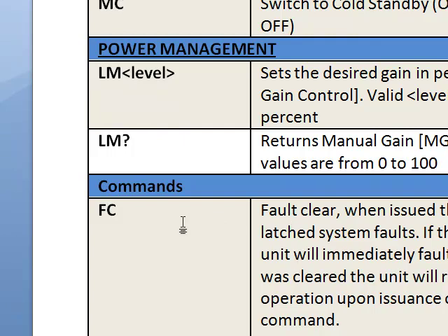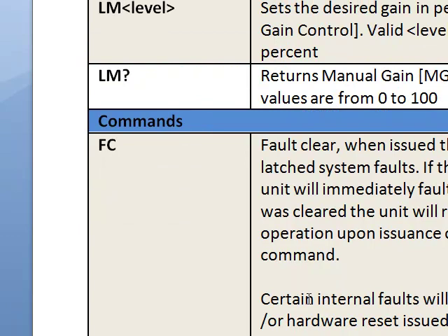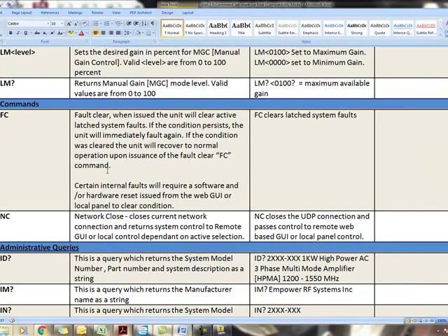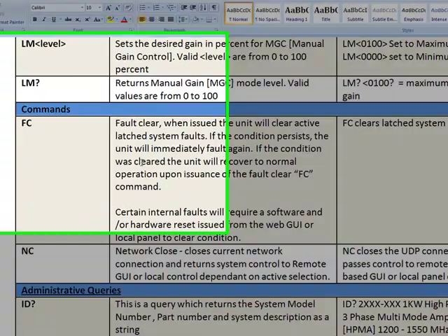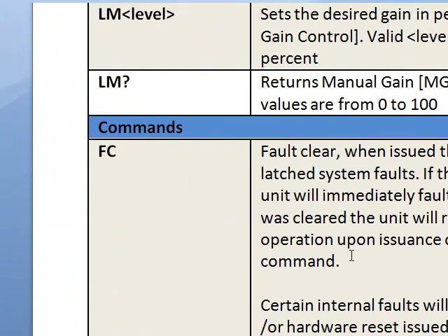This can be sent at any time to clear any of the fault flags that are showing in the SS status message. And the SS status message will automatically push from the device when a fault event occurs. So you will be getting that auto pushed back from the offending element within the system, and you may get one or more of the elements reporting the fault flag.